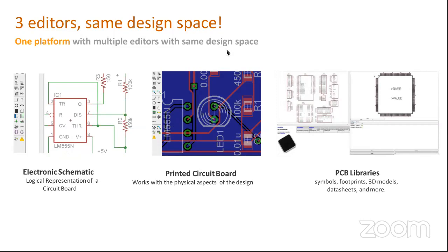Now, the other editor that Eagle has, and they work in conjunction really well, is the board layout editor. In the board layout editor, you're taking into consideration more of the geometry of the circuit board itself. The components that we're using on the circuit board are called footprints. Footprints refers to the amount of copper landing that needs to be on the board, that way you could solder the component. So it's not really the component itself we're working on. We're talking about the amount of copper that needs to be placed on the circuit board, that way I could solder the component itself.